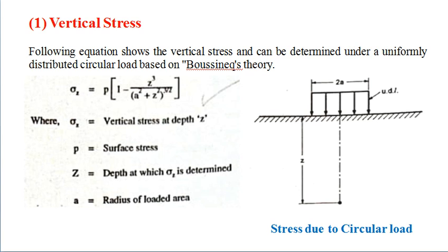Now, as there is no consideration of the self-weight of the soil, hence this top surface of the pavement will be free of the shear stress. That means no shear stress will be considered, and again only the point load at the point of application will be considered, and the stress will be distributed symmetrically with respect to the Z axis, that is the vertical axis.